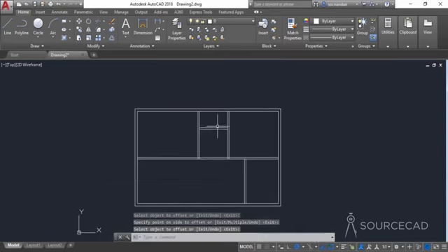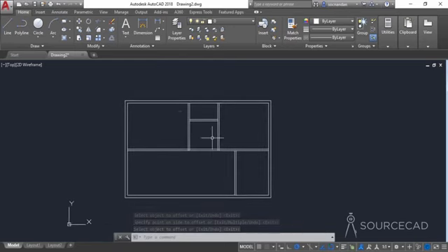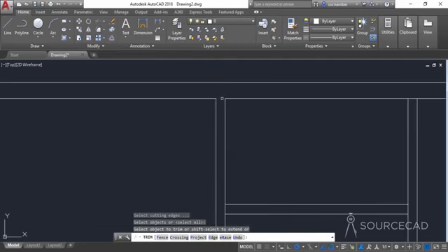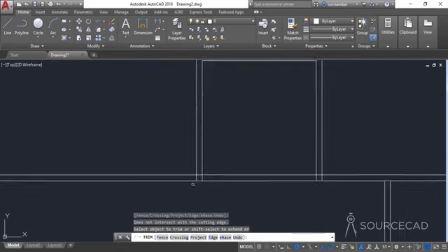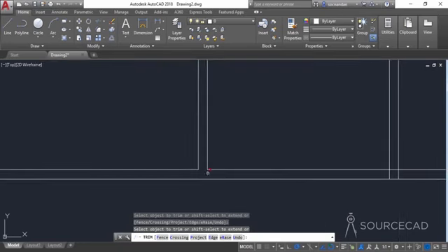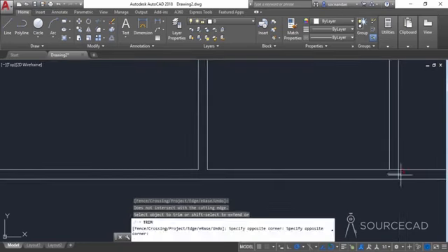All right, now we need to clean this geometry a little bit, and for that I'll select trim tool. So select it and press enter. Now carefully remove these parts of the drawing. So this area should be cleaned, and here also. So wherever these lines are intersecting, simply clean them.